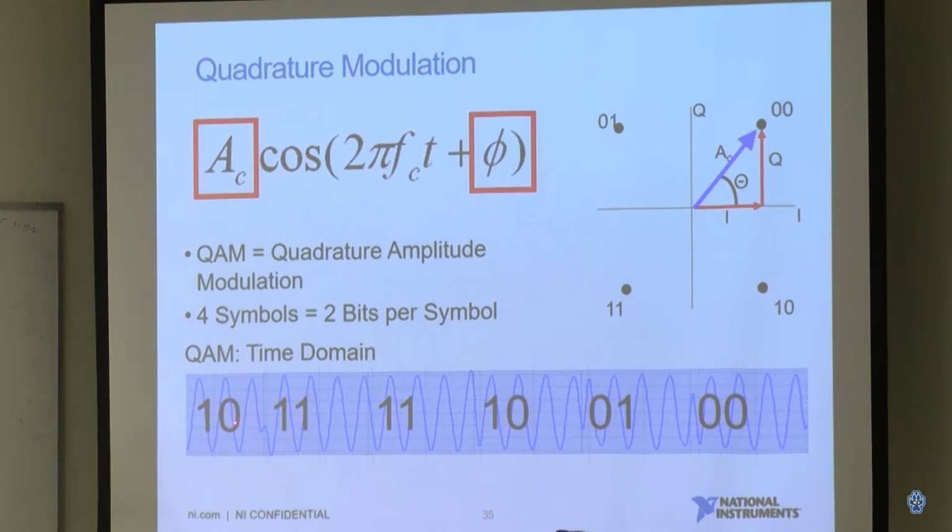scheme in the time domain. Let's say you have 2 bits, so you're using one code for a particular area in frequency, and using 1 1, or 1 0, or 0 1, or 0 0. Using these 4 to represent the whole signal you try to transmit. Remember, if you have higher symbols, you can use more bits to represent a particular frequency to be more robust when sending the signal, so you can send more data. If you have 4 symbols, you can only represent four areas, right? So you can only send a particular amount of data. But if you have 100 symbols or 256 symbols, that means you can use all these symbols to send more data.